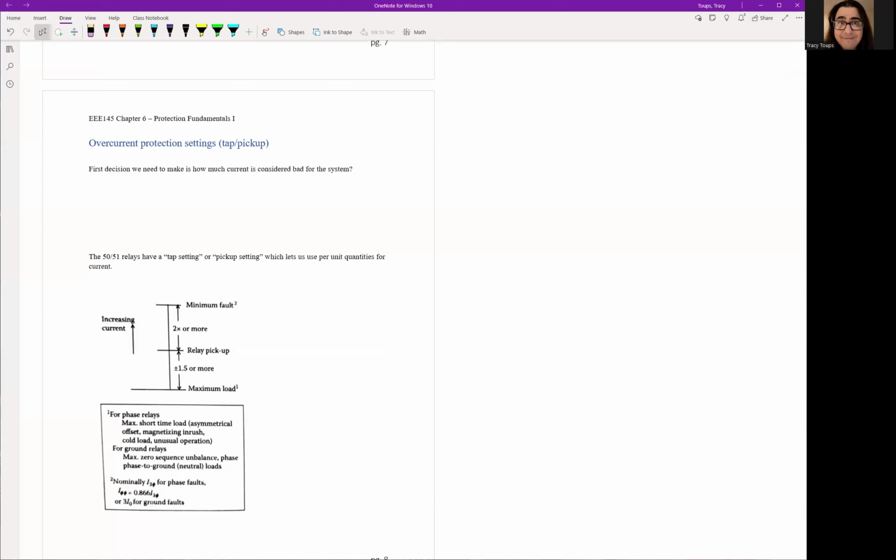And then we could talk about microprocessor relays. They just use literally hard programming, but they mimic the exact function of the disk. So there are a lot of mathematical models, literally physics-level mathematical models, to mimic the speed of that disk and the magnetic field, okay? So at the end of the day, just remember a microprocessor relay has the same tap settings and same time dial, all those mechanical relay aspects are pre-programmed and mathematically modeled in a microprocessor relay.